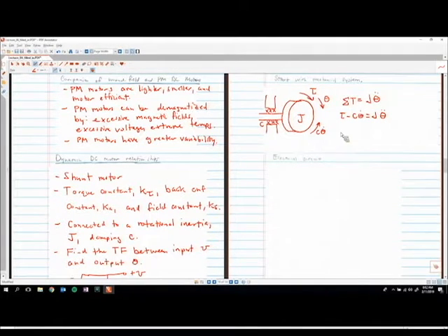So now remember, we haven't gotten to this yet, but we talked about the static or basically steady state motor conditions. We said that the torque for a motor is given by K tau, the flux from the stator in that motor, and then the current running through the armature. Right? These are the equations that we described. Right? This is the same for the static case. All right. So any questions on the mechanical part of this system?